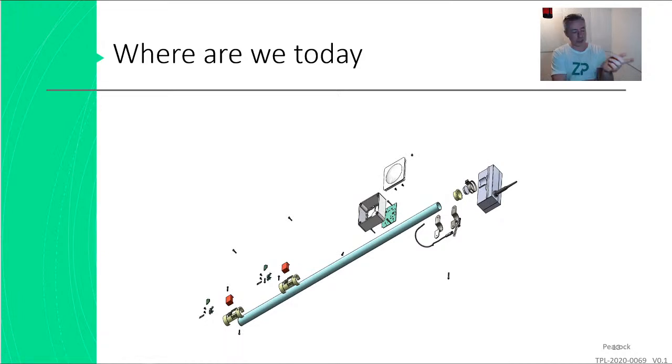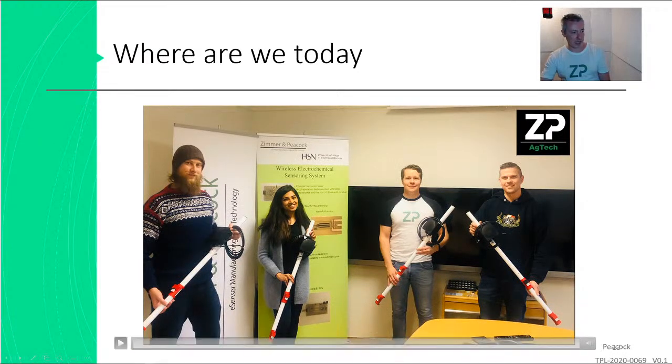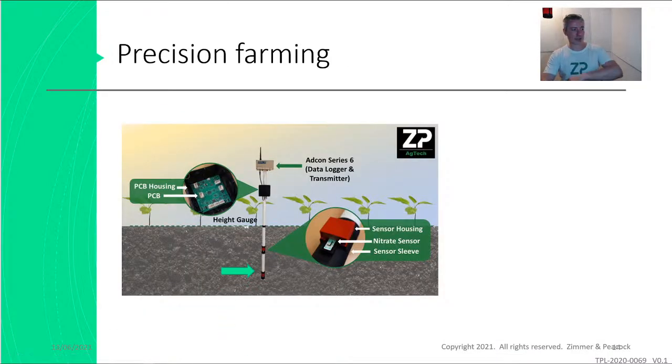But I just want to show that these nitrate sensors, we've incorporated them into quite a lot of technology, which reflects that we have great skill in making biosensors and screen printed electrodes, but we also have great skill in the electromechanical side. This is our engineers, led by the project manager Niti, and you can see we've got these rods, and these red zones indicate there's a little electrode here and a little electrode there, and those are the nitrate sensors. As I said, these rods go into the soil and deliver one nitrate sensor at 60 centimeters and another at 30 centimeters.